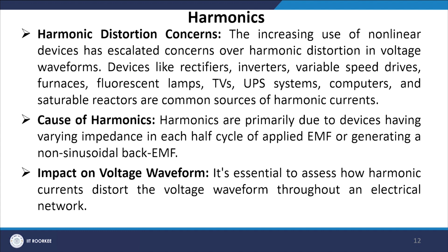Devices like rectifiers, inverters, variable speed drives, furnaces, fluorescent lamps, TVs, UPS, computers and saturable reactors are the major sources of harmonic currents. Harmonics are primarily due to devices having varying impedance in each half cycle of applied EMF or generating a non-sinusoidal back EMF.